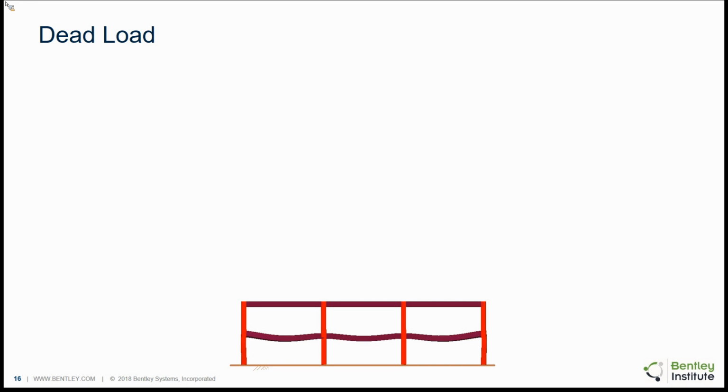And the column shortening now is all built out for this next level. It's all level and it's in place, and they remove the shoring, and that story displaces. And the impacts at the load from that story now are also loading the story below. And so forth and so on.